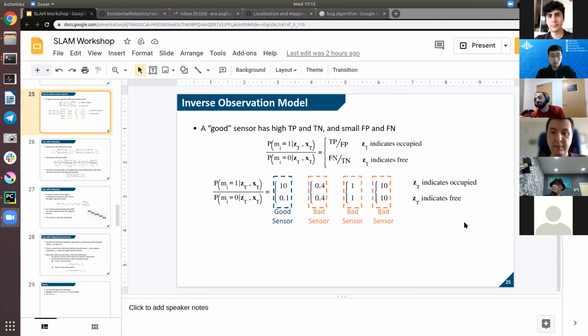Yeah, for Mark, it also would make sense. It depends on your sensor. If your sensor's accuracy decreases with the distance, definitely it's a good idea to decrease lambda by distance. Basically, the type of delta lambda we used here is super basic. People use fancier distance-dependent or position-dependent delta lambdas as well, which is called an inverse observation model. I mean, that's the name you may see in the publications.